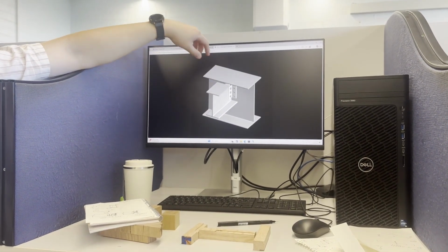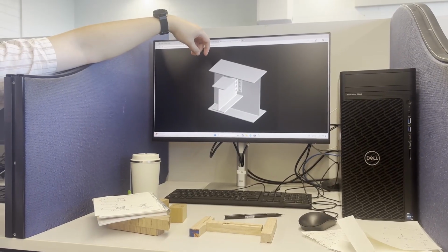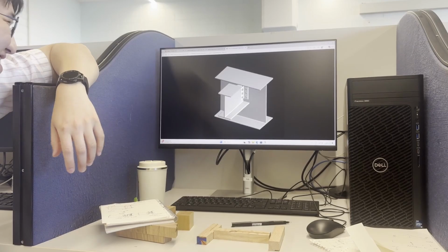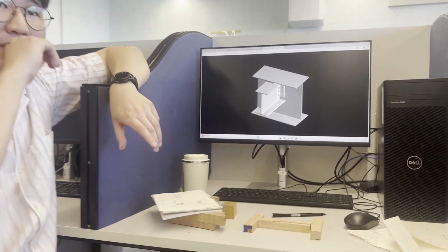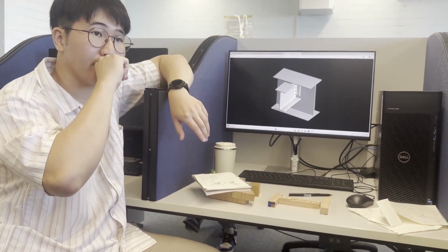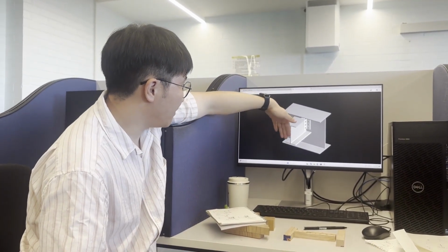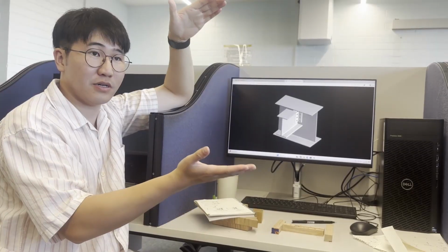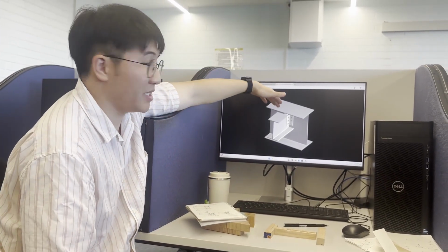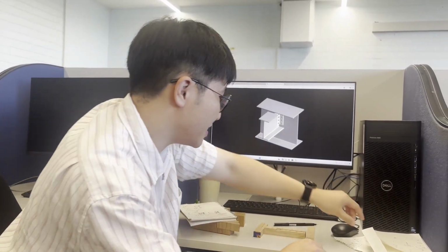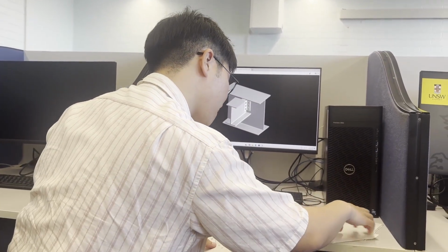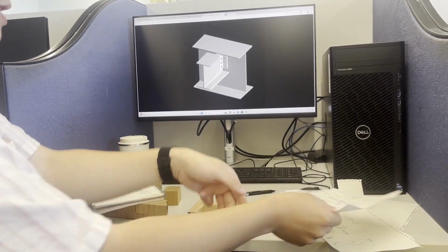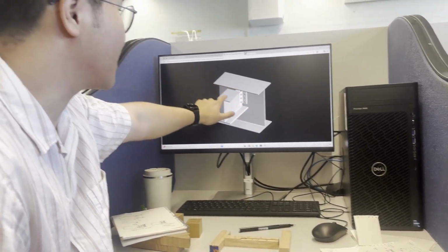Oh, so you just take a chunk of the flange, yep, so it's closer. So remember what the flange does. Oh wait, no, you haven't learned bending yet. Okay, so basically what you'll find is, you know, moment of inertia calculations? The flange for an I-beam basically adds as much meat to the outside as possible, and that gives you a higher moment of inertia, so it's better against bending. But remember our bending moment diagram? This one. You got the least bending at the connection. So it doesn't actually have to take much bending here. It takes mostly shear here.